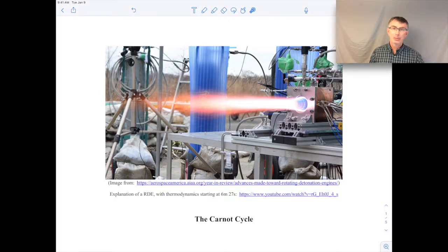And the efficiency comes about due to the following. If you recall the thermal efficiency for a power cycle, it's going to be the work that you generate from the power cycle divided by the energy put into it via heat transfer. That's like burning the fuel. If you're burning the same fuel, assume that QH is a constant. So if you're going to have higher efficiency, then you're going to have a larger amount of work that you're getting out of it. And the larger amount of work that comes out of it has to do with the type of path that the cycle traces out in a PV plot.